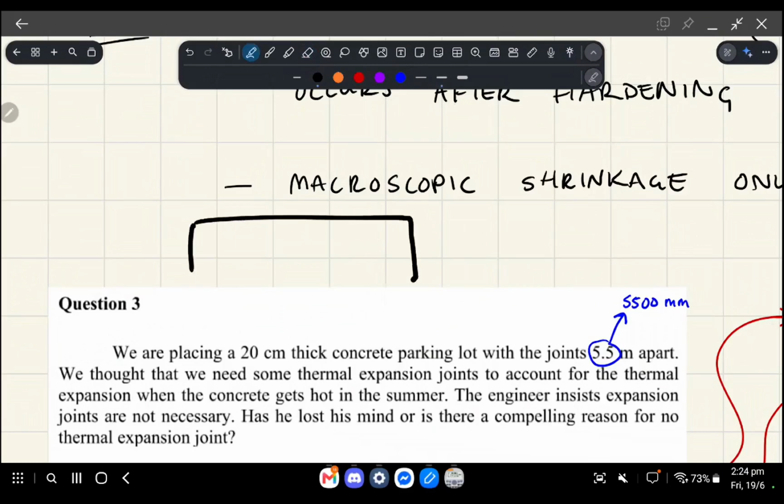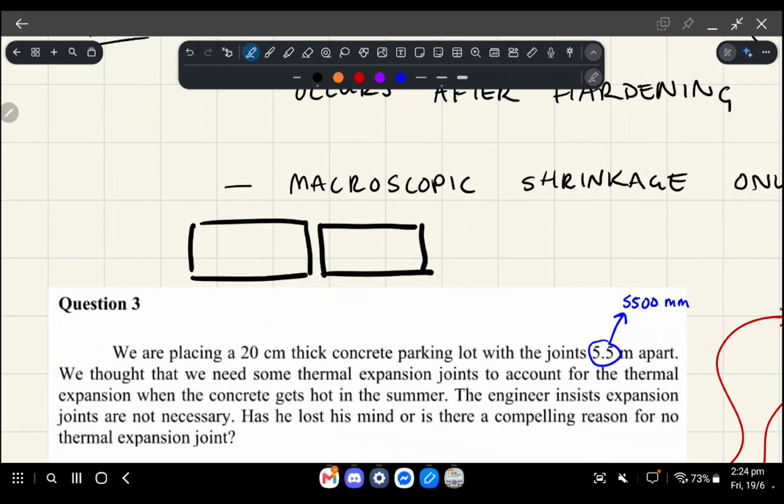So that same block of concrete, instead of a crack forming due to shrinkage, you would instead put something called a joint there, okay? So a joint is basically a predetermined spot for a crack, right? So it's just a place where the concrete is separated. So that's a man-made crack, essentially, right? But it's nice and even, so it doesn't look ugly, okay?